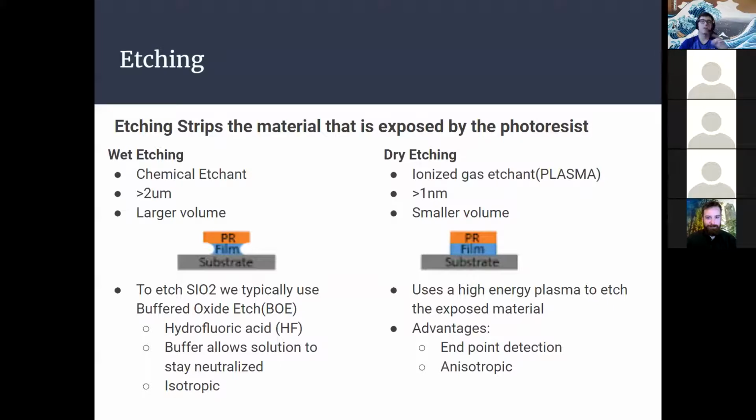Or no, what was the etch rate of the BOE, Colin? It was how fast? It was relatively slow. I think it was around 5 nanometers a minute or something like that. 6, I don't know. Either way, it's a very controlled reaction rather than pure hydrofluoric acid, which would probably just go straight through the silicon dioxide layer. It actually is a very controlled reaction where you can time it using a normal stopwatch and be able to get pretty consistent precision with what you're looking for.